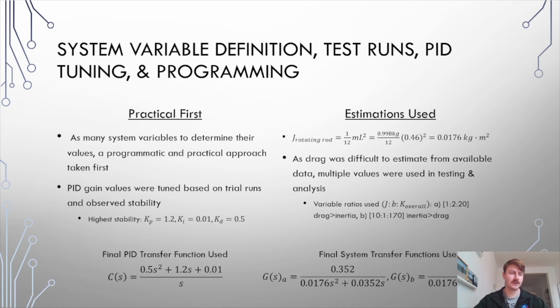Because I didn't have any way to measure the data coming back from the flights, I ended up just running the flight, testing its performance characteristics, and adjusting things in gradual steps until it provided a fairly stable flight pattern and stability control. So the variables ended up being defined here, and you can see the final transfer function for the PID.